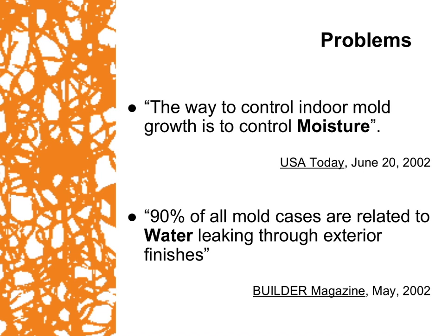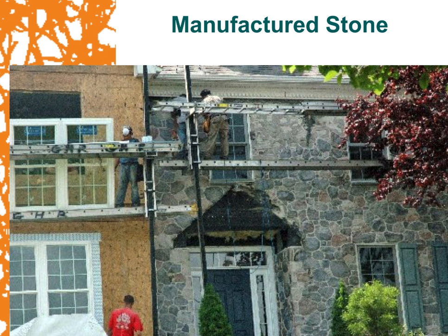These are examples that show moisture will not only deteriorate our building products and cause problems on the outside of our building, but can also cause problems for the indoor air quality and indoor health of our buildings from a mold standpoint. Next, we will go over some pictures that show the worst case scenario when it comes to moisture damage or moisture intrusion behind our facades.